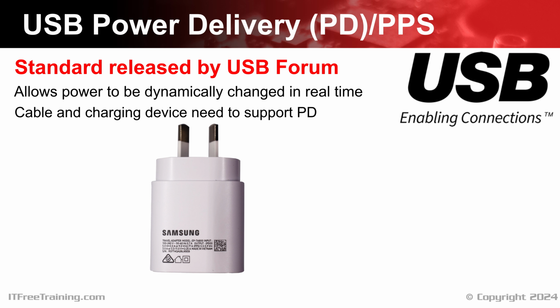In order for PD to work, the charger and the cable must both have electronics in them that communicate with each other. Essentially, the charger asks the cable what power it can support and makes sure it does not go over this. The device attached is free to request whatever power it needs in that range. This way, the charger does not send more power to the cable than it supports.